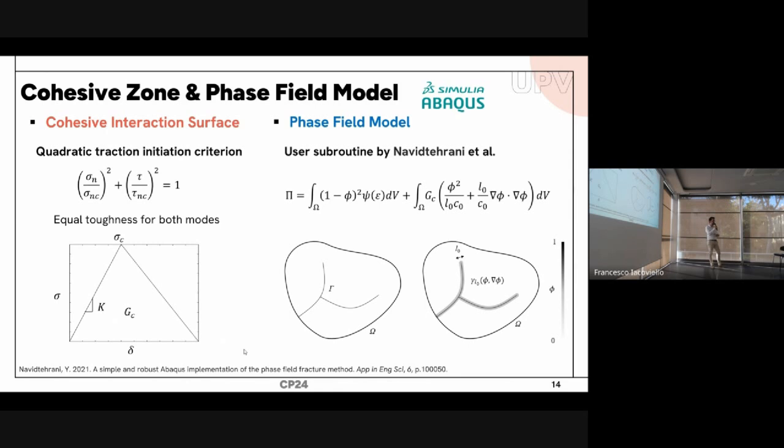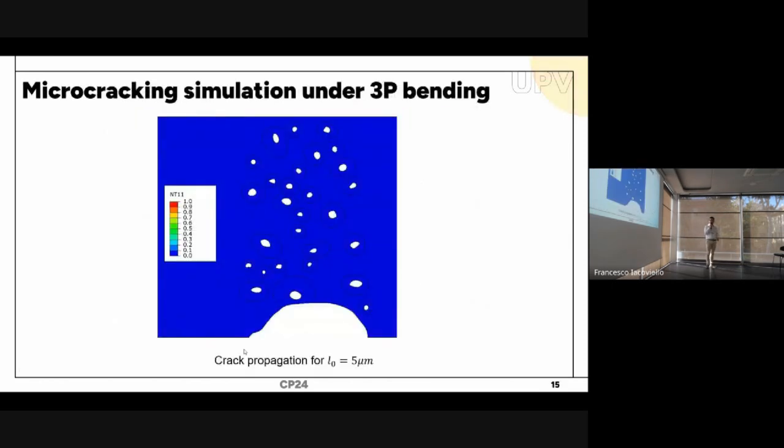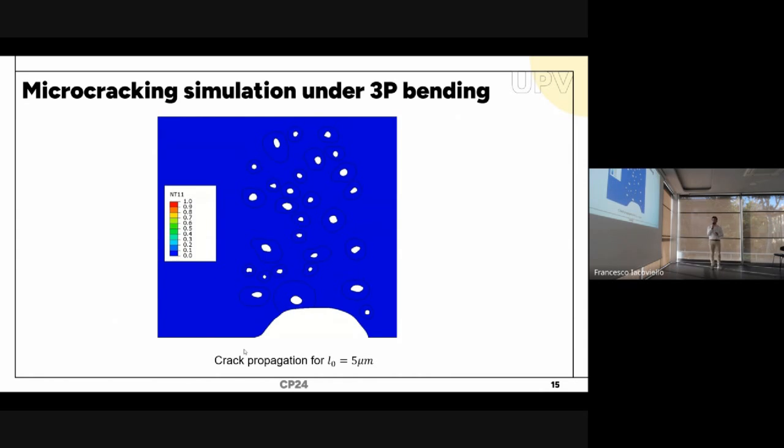So the properties for the interstitial bond were taken from the literature. And with everything, the properties that we calculated before for the cement lines and the new properties from the literature for the interstitial bond, we could run our simulation. Here we can see how the load is being applied from the upper side. And over here, we'll see how the interface starts fading, and then a quick propagation of crack goes upward. Here, the crack propagates from one failed interface to another in the form of a phase field crack, which is the variable that we are plotting here.